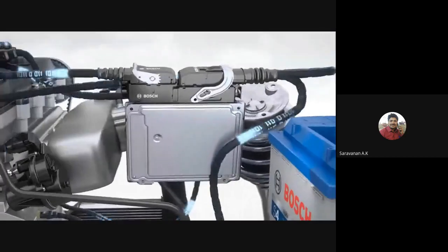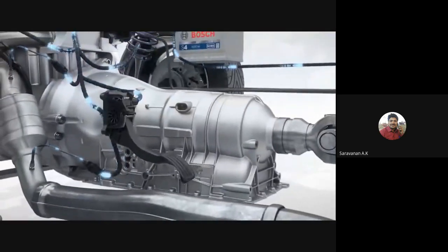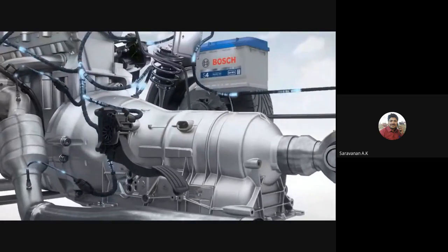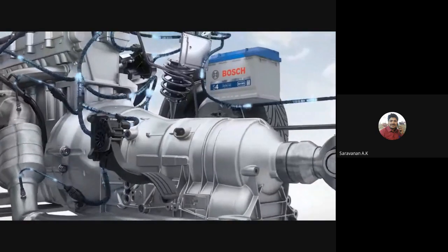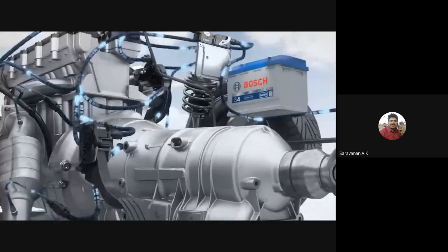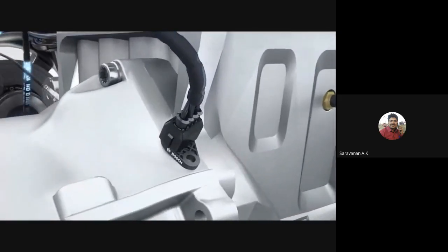Bosch Engine Control supplies the numerous functions that an efficient engine management system must provide. The driver's wish for more or less power is an important input variable for the electronic control. The accelerator pedal module supplies the driver's wish as a sensor signal. The crankshaft sensor registers the speed and position of the crankshaft. Additional data is provided by the knock sensor, the temperature sensor, and the camshaft sensor.